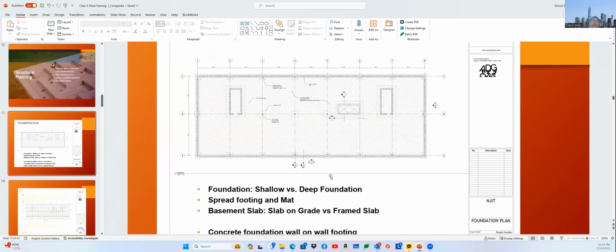What you're looking at is a foundation system. Our foundation system is much heavier, but this is low-rise. I'll just explain. But you're already familiar with foundation walls. A wall needs a footing, wall footing. A column, I think, is sitting on the wall, so we need a concrete pier, right? Also two stairs. I assume these will be made out of concrete wall. And the elevator shaft wall, I made this one as shaft concrete shear wall.